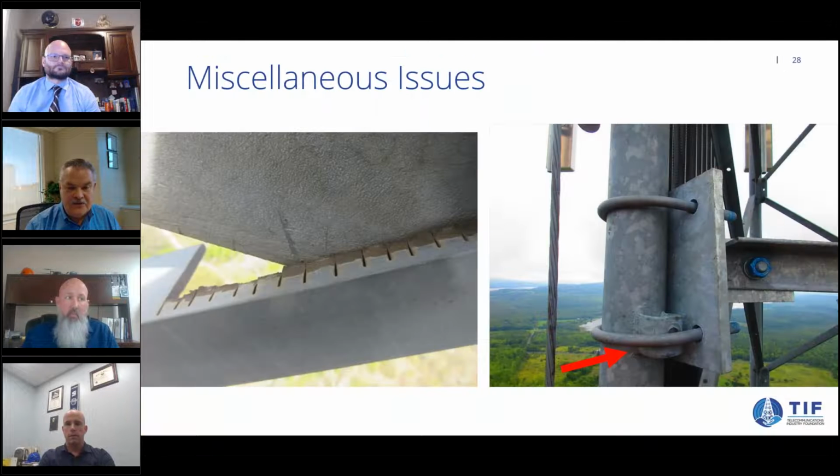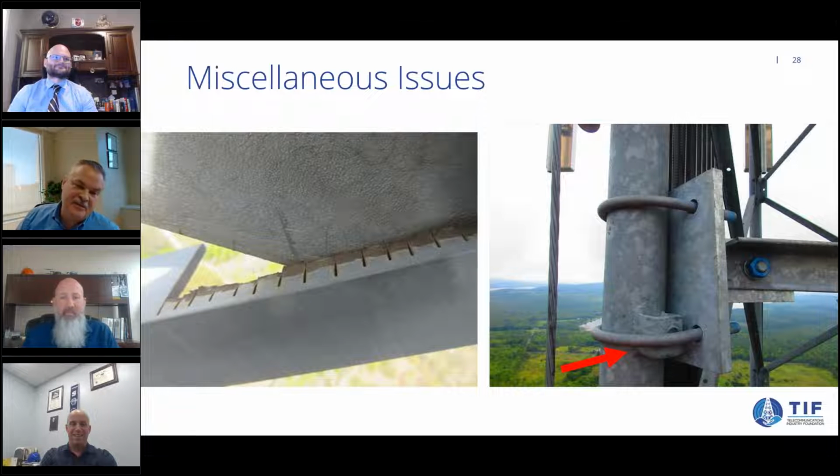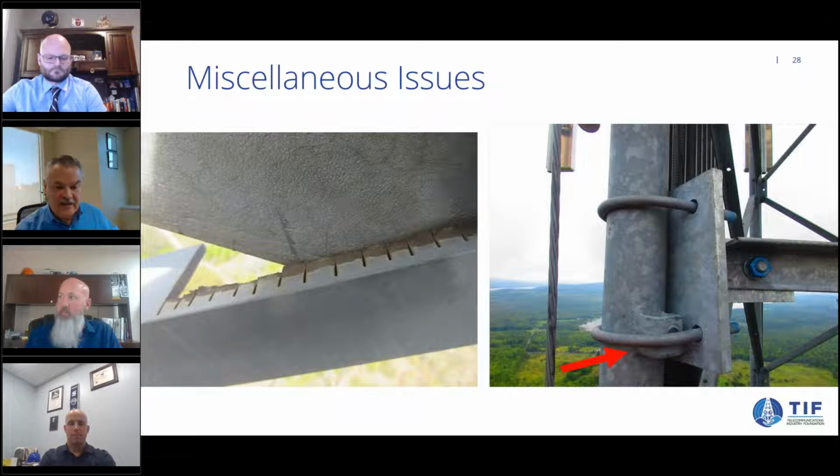A couple of structural issues. One on the left, John and I don't appreciate this because you always have an angle member where somebody had to trim it to fit. But what you've done is you created, instead of an angle, basically a flat plate with some perforations and cuts on one side. It has nowhere near the load carrying capacity it once had.